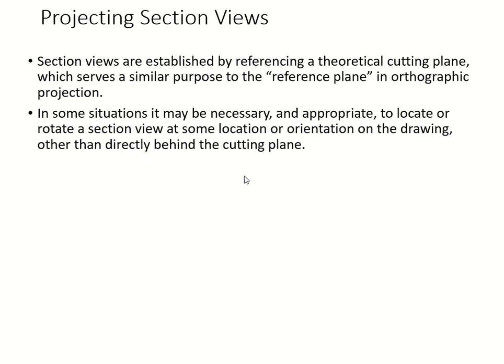Of course, you also need to know where to cut it, because the features are sometimes very complicated. Even though you cut, you can't necessarily see or describe other features hidden between the cut line and the original plane. So you have to figure out what features you're dealing with on your model, so that you can cut and be able to see them. And when you see them, we usually use different symbols in a drawing to show that this is a section view, this is the auxiliary view, and that is the orthographic projection view.